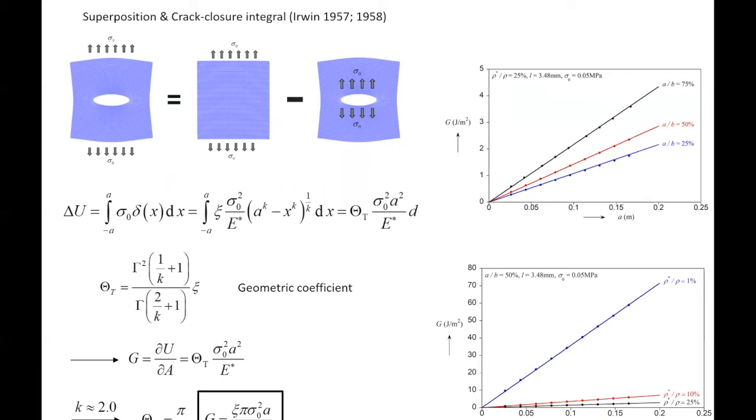All right. One stress. In fact, you could argue that in a lattice there is no toughness. All there is is strength, because if I'm looking locally, you have a geometry that has no singularity, and it's going to break because some, let's say, tensile strength is going to be reached. And that little thingy is going to break. Okay. If you were to use the model that you presented before to model this system where you can take strata, what would you get? That's one question. And why don't you use that?